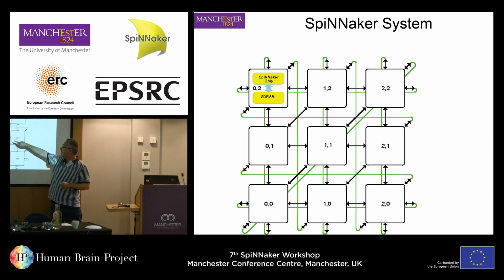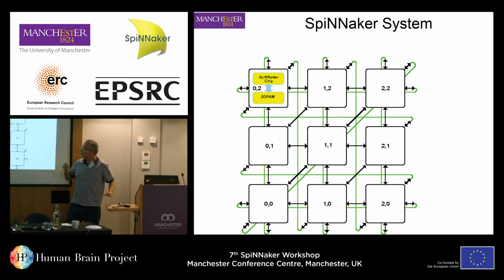The chips connect in a hexagonal mesh, and there is wraparound on the edge of systems, so that it can be used to form an entire torus. So when the chips are operating together, all they see are 6 links going out across a 2-dimensional sheet in all directions. Now, one of the main things that's particular about SpiNNaker is the way that this communication infrastructure works.